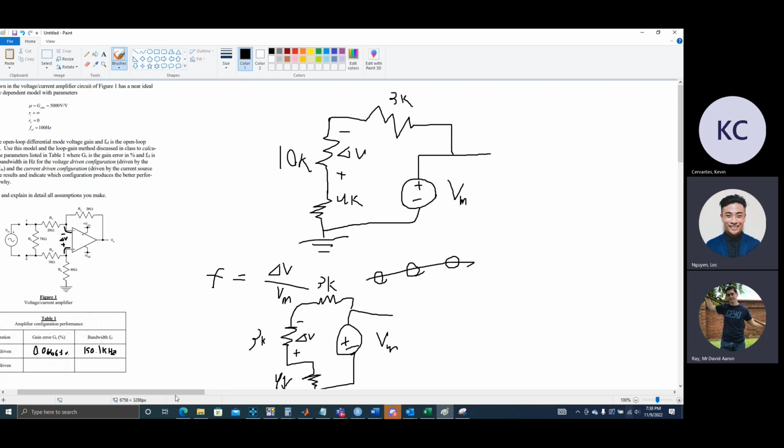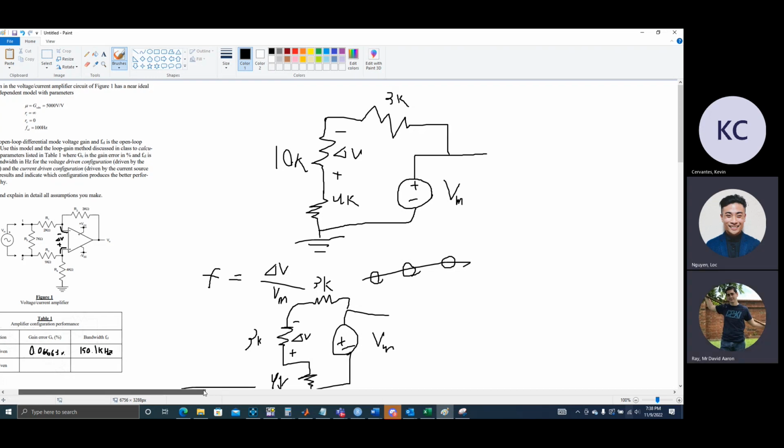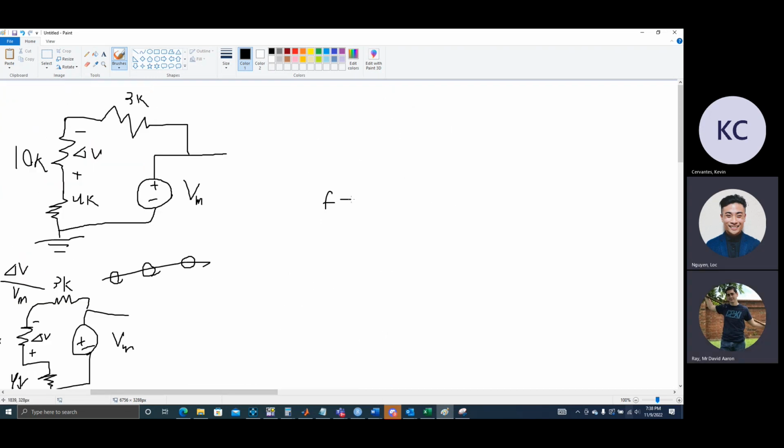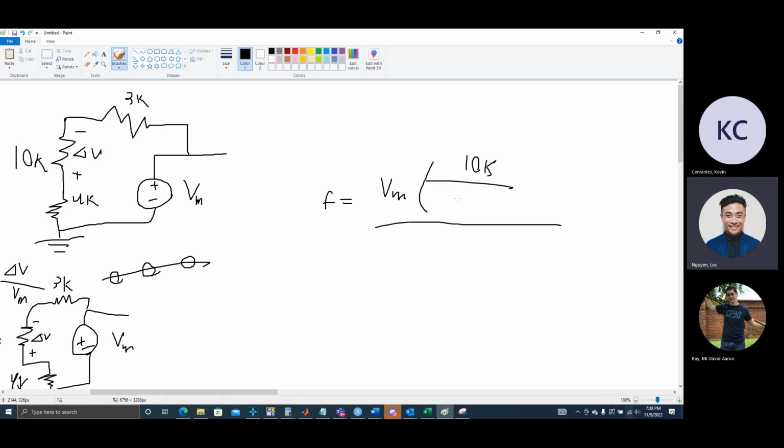So now that's just gonna look like what you said, that F is equal to, sorry, yeah. I can do Vm times your 10K over 10K plus 4K plus 3K.